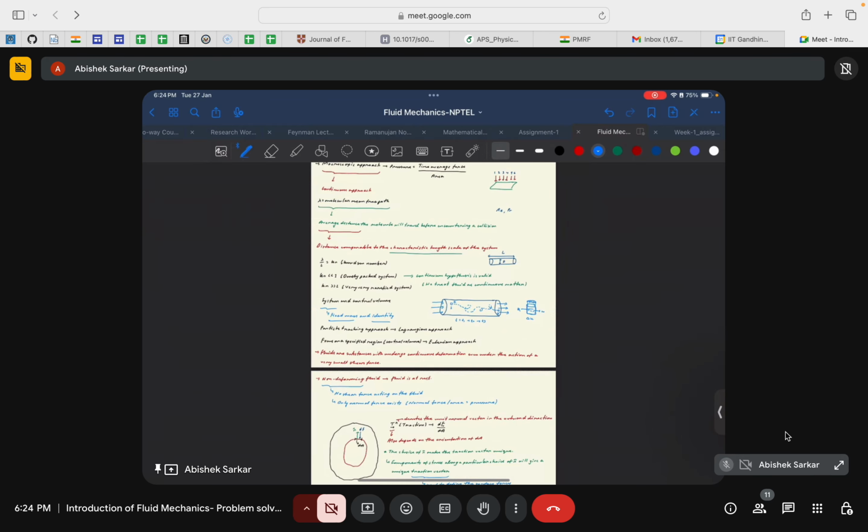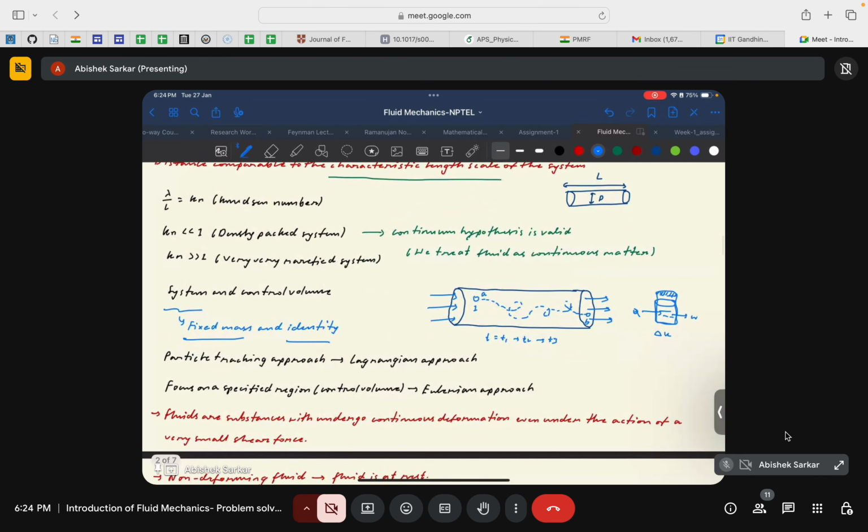Okay, fine, it's completely all right. In this case also, it will come under the paradigm of control system, primarily because, why? This definition is important. The mass is not changing because there is no fluid going out of the container through evaporation, because I've closed the lid, and since it is not going out, the identity of the fluid molecules remains constant. So any kind of physical phenomenon that occurs within this fixed closed system can be treated with a control system approach.